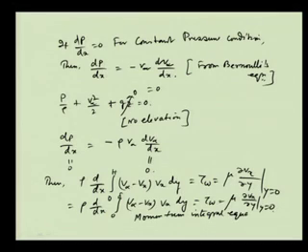We can see that we have changed the integral limit from 0 to h to 0 to delta, because when h is greater than delta, V infinity and V x are the same. So this integrand will become 0, and it will be useless. So it is better to write 0 to delta.